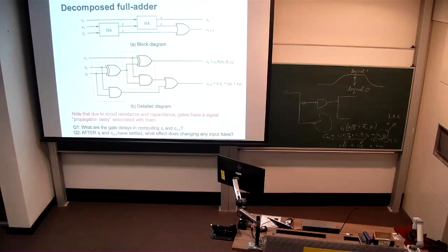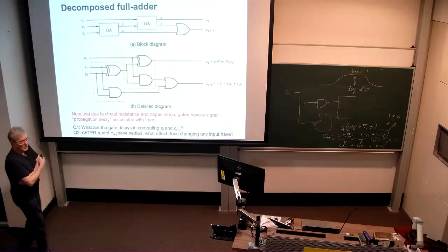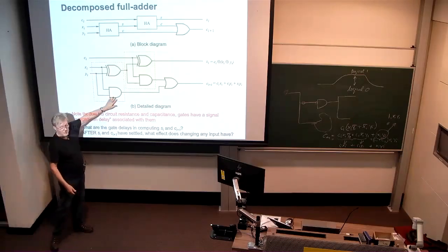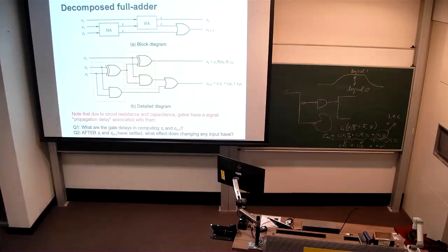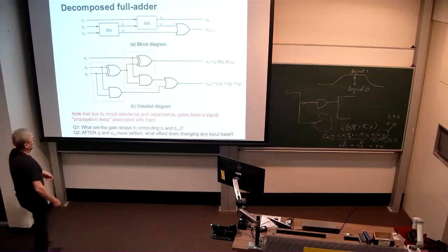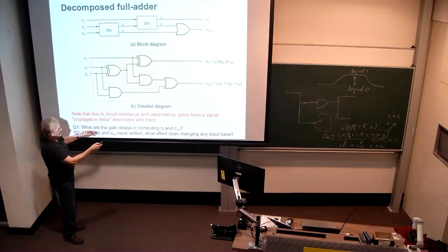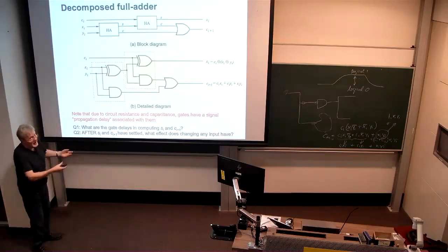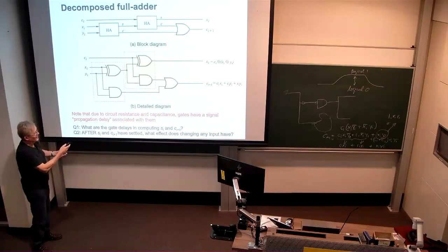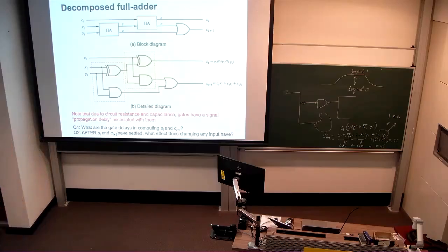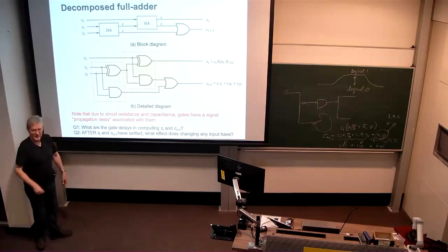So when I looked it up, actually, I got the impression that this is probably going to be, at very least, about 120 to 130 picoseconds for 65 nanometers, where it's only 20 to 30 picoseconds for 65 nanometer AND gates. So there's about a 3-fold difference in delay. And as for the delay for the sum, well, it's at least 2 gate delays, but we know that this is a bit of a fake, that this is not single gates. We're probably talking more like 6 gate delays, so it's quite a large delay that we're talking about as far as getting the sum out.